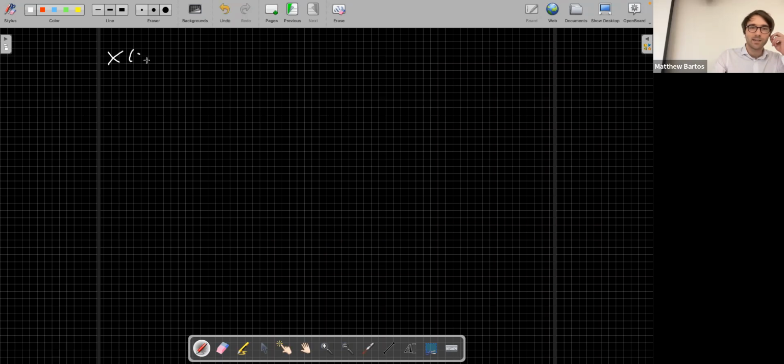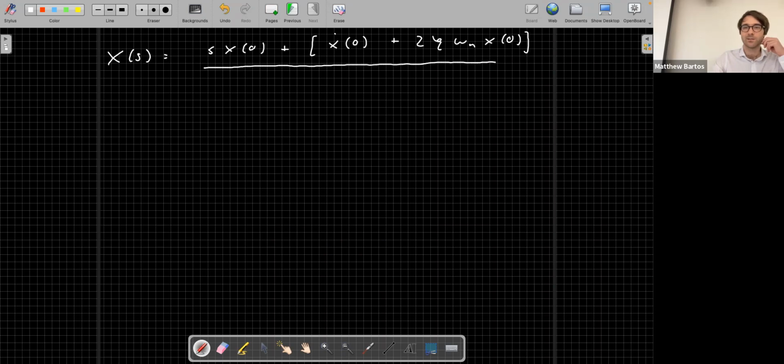All right. And so what we end up with is X of s, which we can now write as follows. We have our numerator, same as before, s times x at time 0, plus quantity x dot at time 0 plus 2 times zeta times omega n times x at time 0, all over our new denominator, s plus zeta times the natural frequency all squared plus omega d squared.